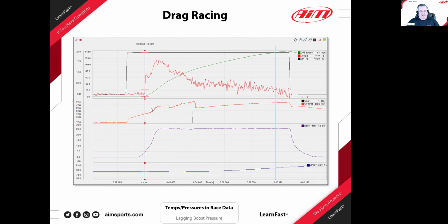And then I start to study why the inconsistency. This is what my dad was asking me and my brother, who drives it. We're inconsistent on our 0 to 60 foot times, and we're trying to understand why the car leaves the start line really good sometimes, and sometimes it doesn't. So we put in the data system, we're reviewing, and here's the throttle trace. This black one goes up to 100% as he's sitting there waiting for the light.